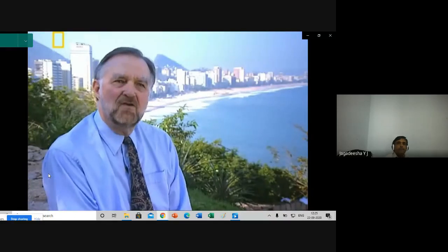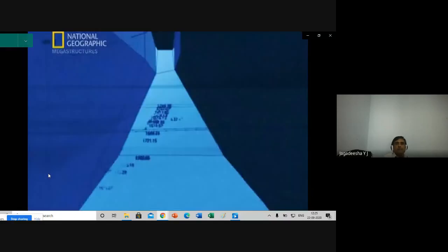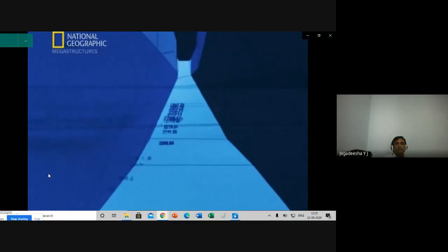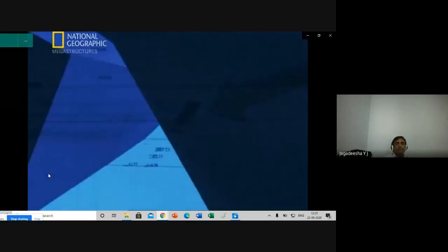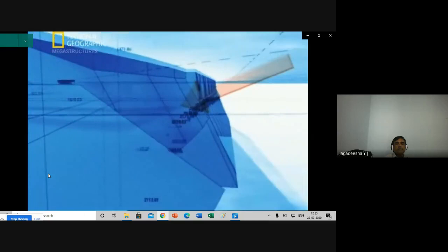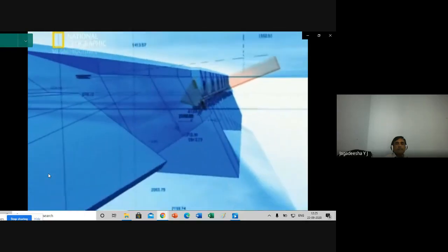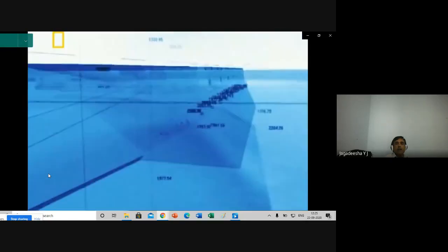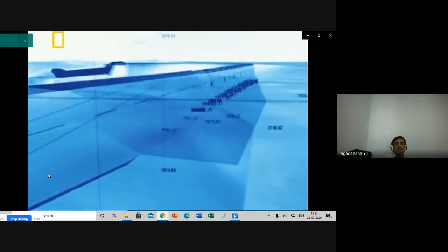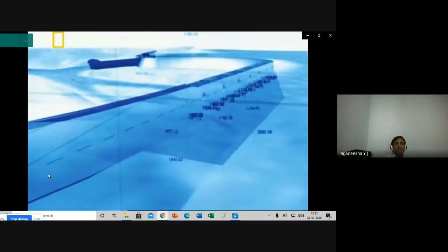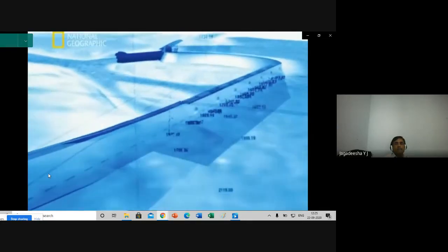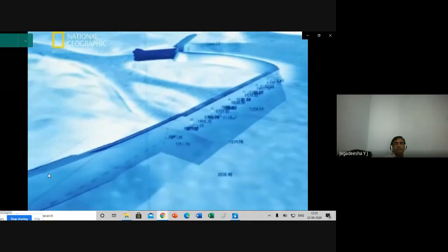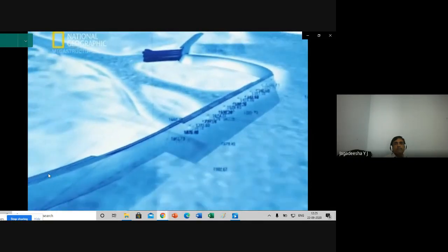It can be hollow and still resist the water pressure. Building the dam hollow meant its base could be made even wider with the same amount of concrete, and the walls would slope more gently, pushing the water pressure down to the base where the dam is strongest. It also meant the power generating equipment could be housed inside the dam itself. It was a clever solution.